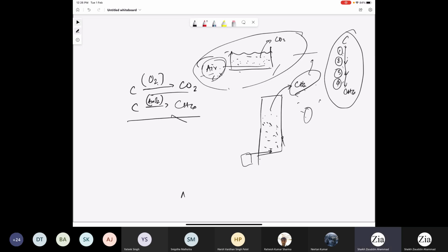The problem with low strength wastewater is you will not get a sufficient amount of methane. Also, whenever you have low strength or low carbon wastewater, the granules present in the anaerobic reactor will not be very stable. If you have a low concentration of carbon in this series of reactions, you will have some sort of substrate limitation in one of the steps, and obviously the subsequent step will not go further, and that will also impact the biomass present in that particular group.